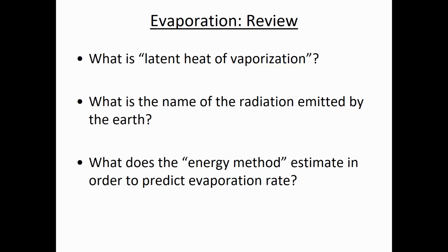Now there's also some reflection, but the main idea is it's an energy balance that looks at the incoming solar radiation and the outgoing long-wave radiation, and says how much is left when you account for those two. You've measured the sun intensity. You have some way of predicting what the long-wave emissions are. And so how much energy is left between the two to vaporize water?